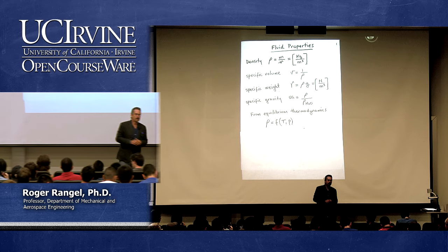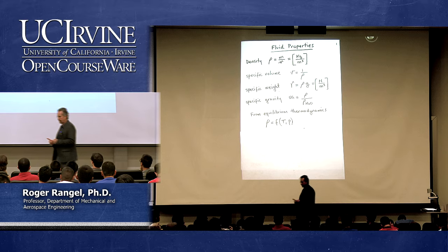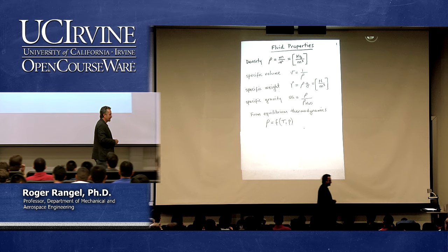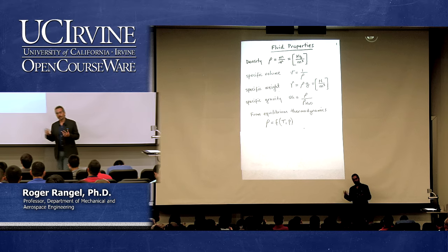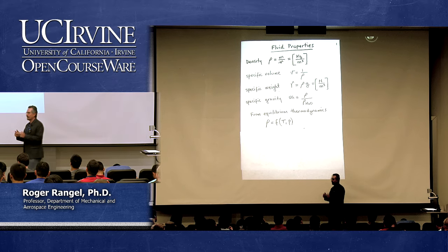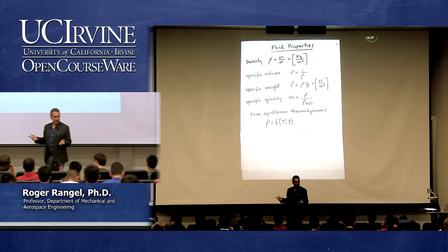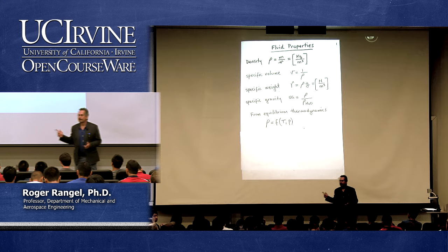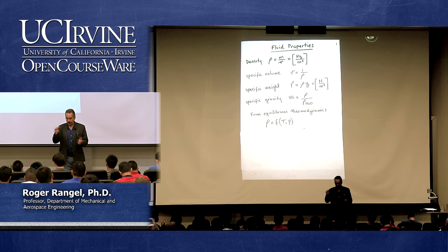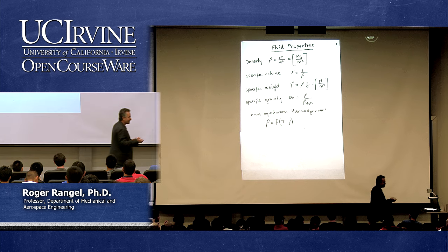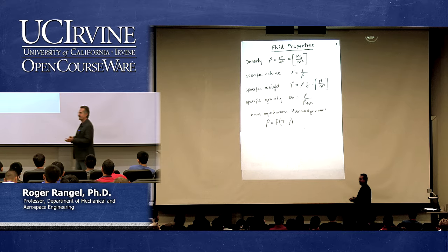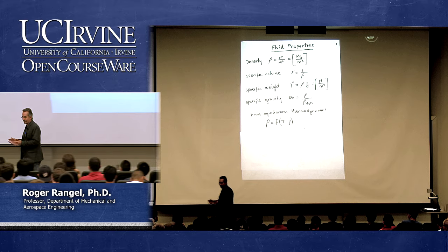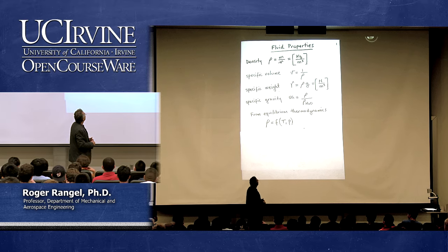They have to be intensive and they have to be independent, meaning that they cannot be linked to each other in any way. And there was only one scenario where you had to worry about properties being linked. Is that ringing a bell? When we had a mixture of liquid and vapor in the dome, then pressure and temperature were linked. So you thought you could forget all about thermodynamics, but you can't.